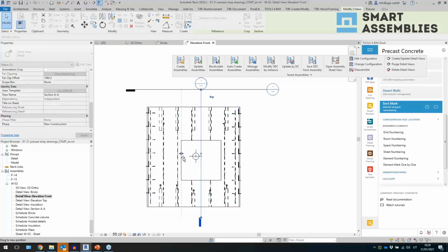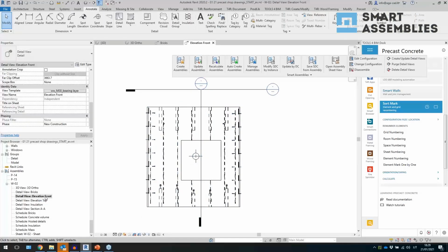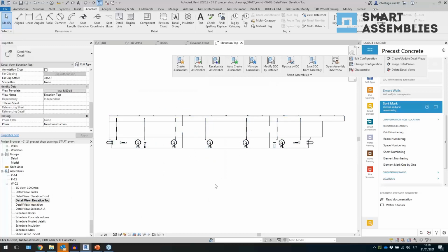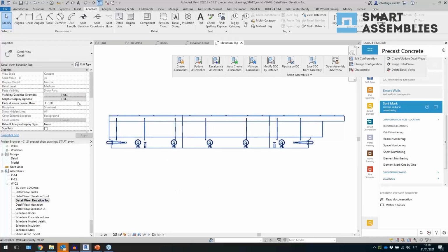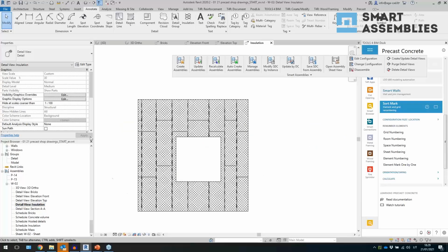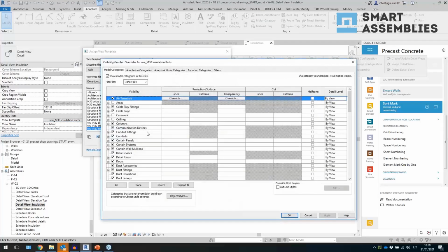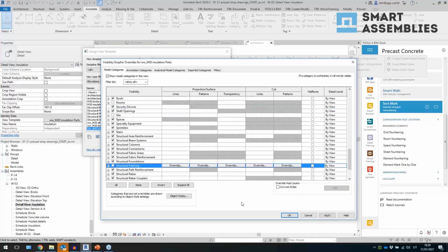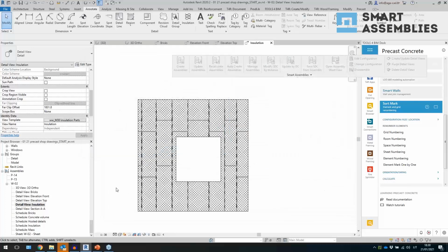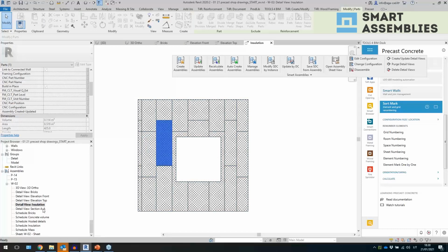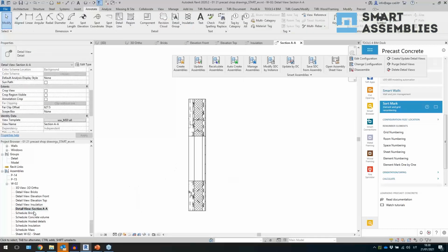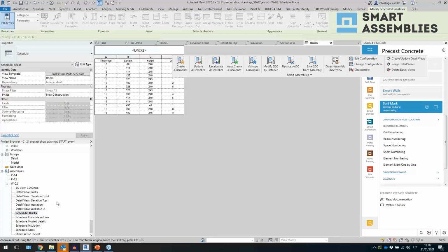I can reduce, let's say, the size of section if I want to, and change the position, and the tool will remember that. What else? So we have this view, then we have this installation view. Again, it has these structural framing elements which I forgot to switch off, so we can do that now. You see, so now I have only these installation elements created, and the section.